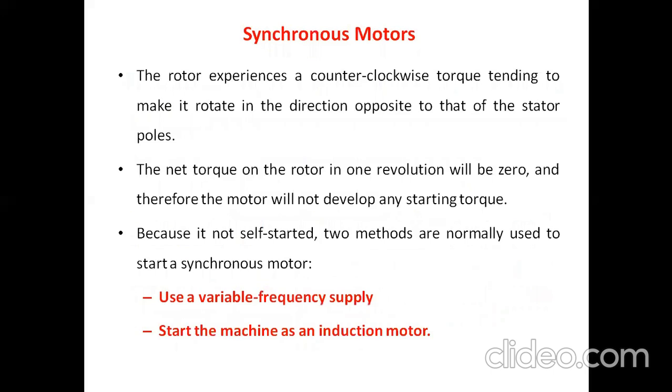Next one, synchronous motor drive. Here the rotor generates a counterclockwise torque, making it rotate in the direction opposite to that of the stator poles. During this condition, the net torque on the rotor over one revolution becomes zero. Therefore, the motor will not develop any starting torque, so it is not self-starting.